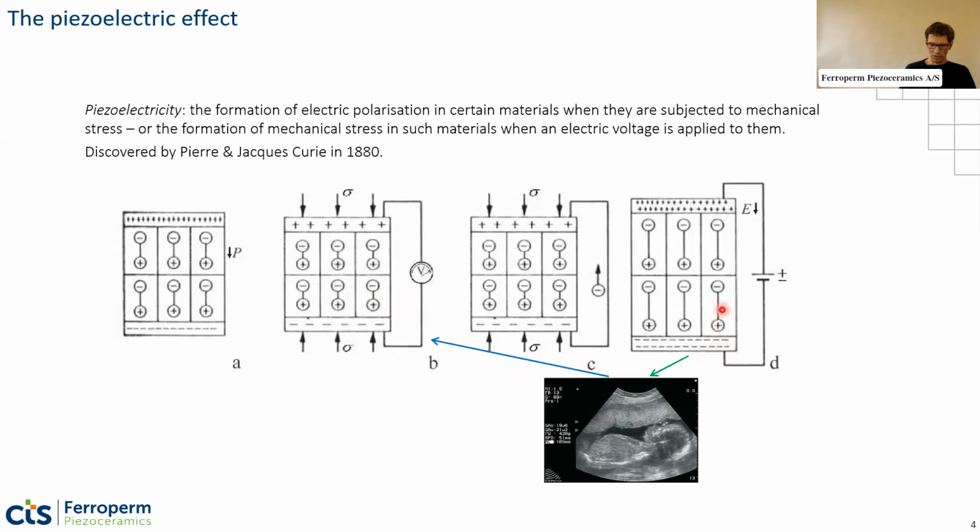So sound generation through this effect, through the direct effect, and then detection of sound echoes through the other effect. And by keeping track of the time differences, you can see the difference between something very close to the sound emitter up here and something far away, because of the time of flight will be different. And also you can detect the angle difference from a time difference, because the scan may go from this angle and then through to this angle and then back again. So, two very simple examples and one quite advanced.